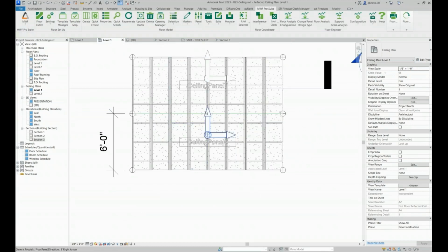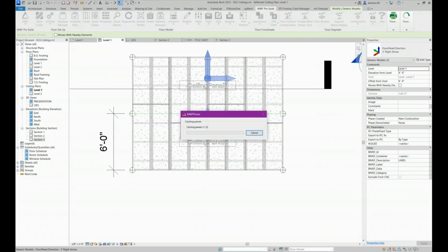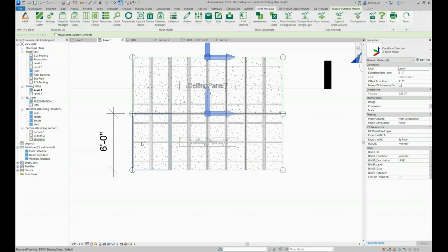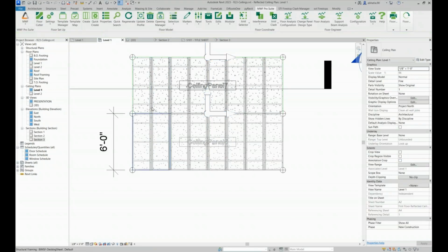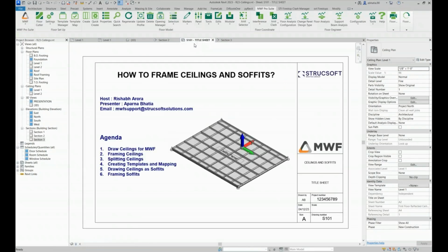And you can notice that if I regenerate these 2, that same marker line will be recognized for both panels. So even though we drew that marker line one time, since it continues till the end here, it will be considered for this panel as well. So you don't have to redraw it. Okay? So that's basically how you would split your panels.